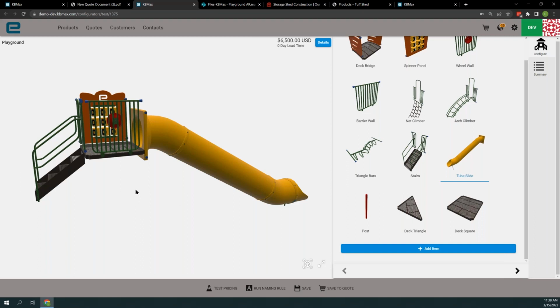right? So far we've added a bunch of static components to this and built out an assembly, and that's great. But there may be cases where we need this to be dynamic. And so if I were to just click on that staircase, we will see some options presented to the user here. So we can actually take these fields and things like that we have inside of the configurator and embed them directly in the 3D scene. So this is extremely powerful and makes for a really nice use case for your users.